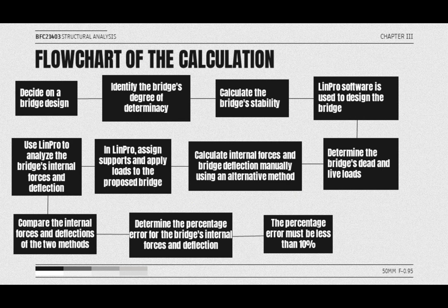Next is the flow of the bridge calculation. For the first step, decide on the bridge design, then identify the bridge degree of determinacy and calculate the bridge stability. Then use LinPro to design the bridge. Then determine the bridge depth and live load, and calculate the internal forces and bridge deflection manually using the alternative method. Then in LinPro, assign support and apply loads to the proposed bridge and use LinPro to analyze the bridge internal forces and deflection. After that, compare the internal force and deflection for the two methods and determine the percentage error, and make sure the percentage error is less than 10%.